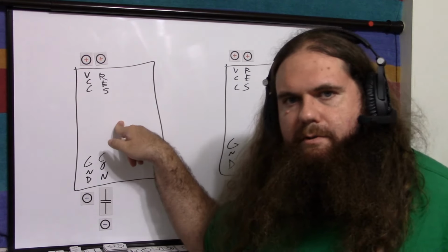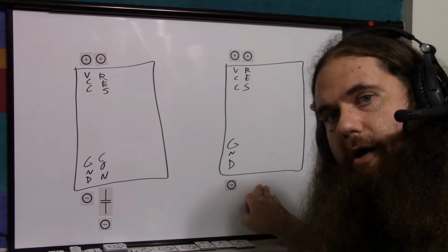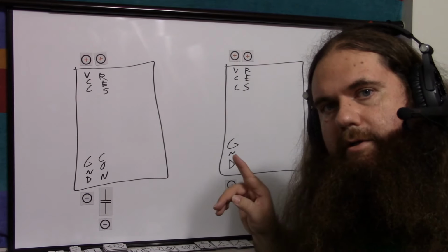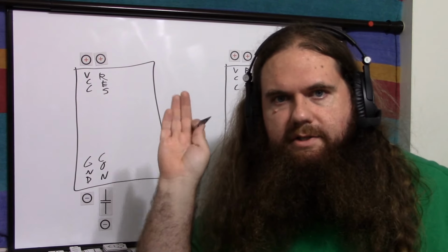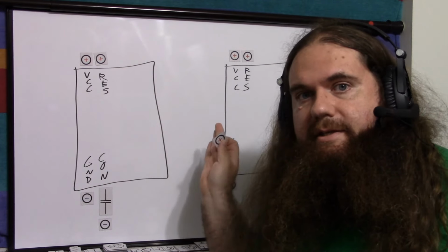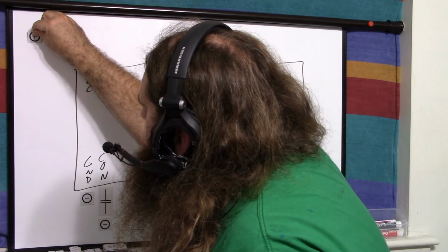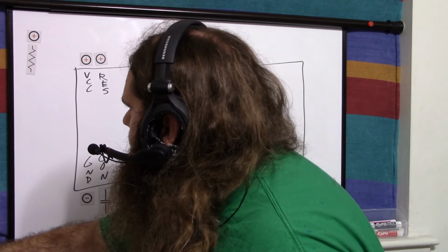This is going to be the square wave generator, the astable. So we're not using the control voltage on this one. I'm going to leave the control voltage on here alone for a moment. For the astable, again, this is just the same. Watch the astable and monostable videos for an explanation. It's exactly the same setup, no changes. So for the astable, we have our 2 resistors and 1 capacitor.